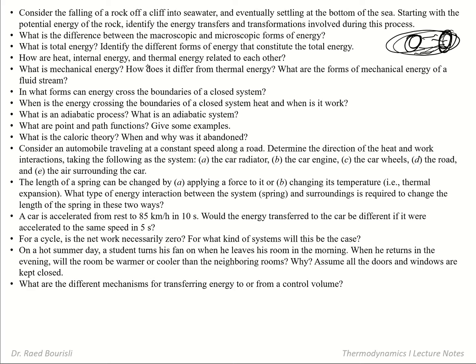What are the forms of the mechanical energy of a fluid stream? This is the kinetic energy, potential energy, as well as the pressure. If you are into mechanical or chemical engineering, or civil engineering, this is what you will discuss later as the conservation of energy, and then it will give rise to the Bernoulli equation, which is just an expression for the mechanical energy of a flowing fluid.